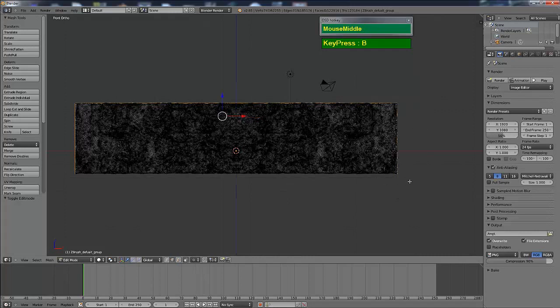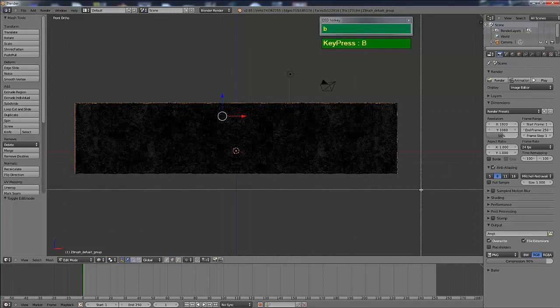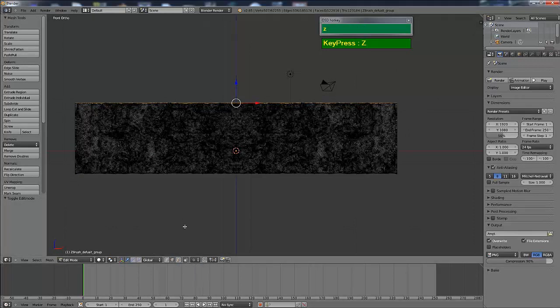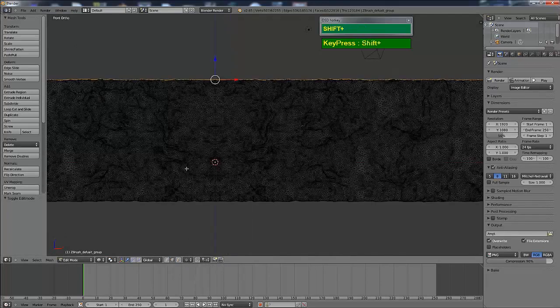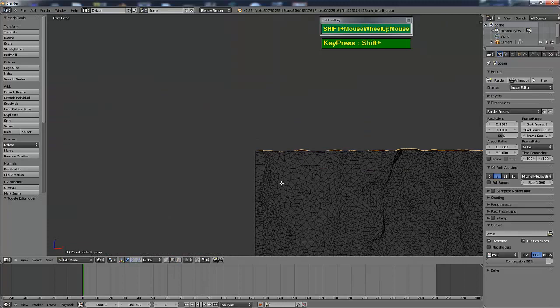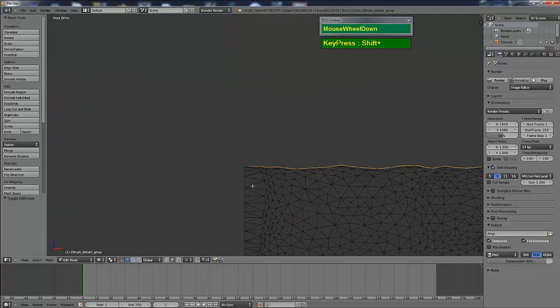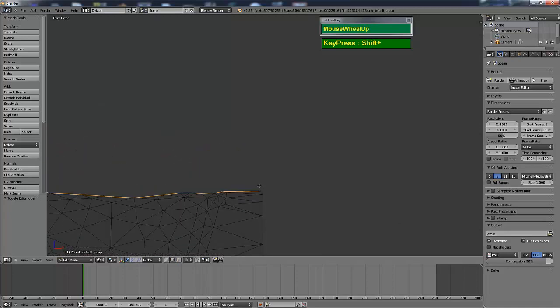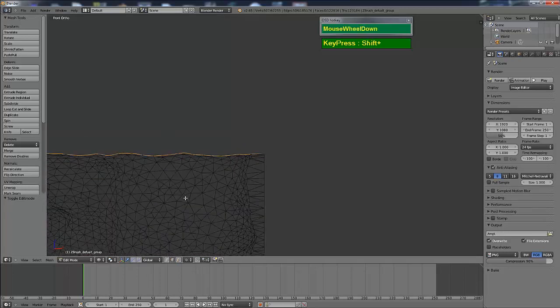I'm going to go to wireframe mode, press C. Okay, sometimes you notice some sections will not be selected. You need to be in wireframe mode to do that. Or you can turn on this, let me go to shaded view. There's this limit selection to visible, but I prefer to select in wireframe mode in this case. Okay, now I just want to inspect and make sure that the top edge is selected. Okay, it's selected. Alright, cool.